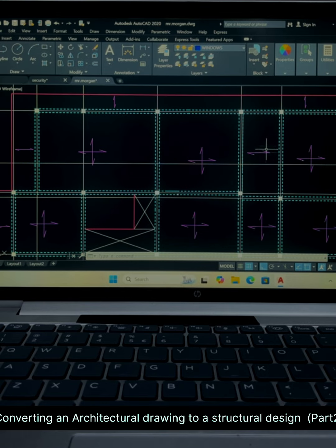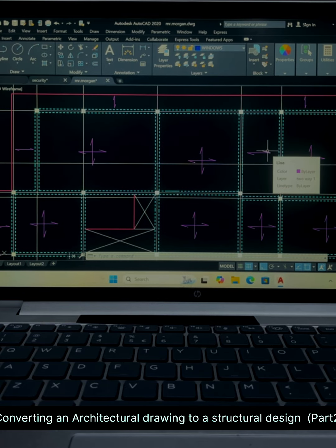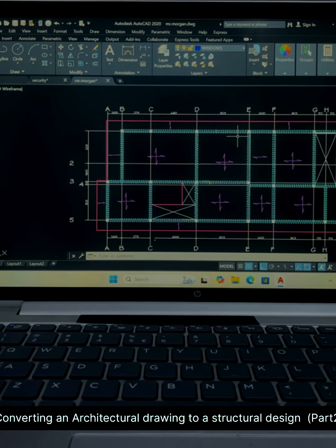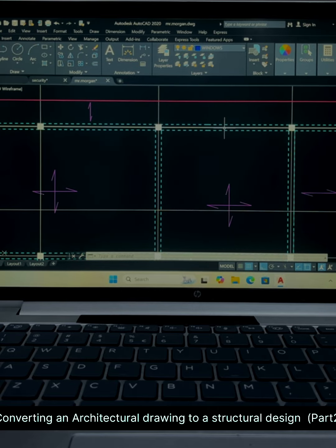It should be greater than 2 and it should be designed as a one-way slab. The beams here are represented with dotted lines because when you stand on the slab, you're not seeing the beams. The beams are downstand beams and you represent them with hidden details.